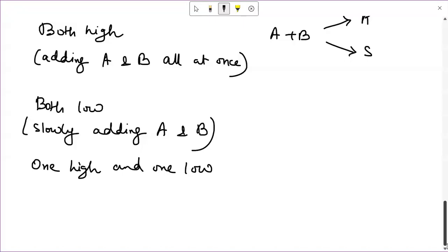Now in general, depending on how many fluids are reacting together and if there is any recycle involved, there are many possibilities of contacting pattern. So you have to study all possible such configurations when you are actually doing an engineering case study. But in any case, the use of proper contacting pattern becomes very critical when you have multiple reactants involved for favoring the product distribution. With this, we come to the end of the qualitative discussion about parallel reactions. Thank you.